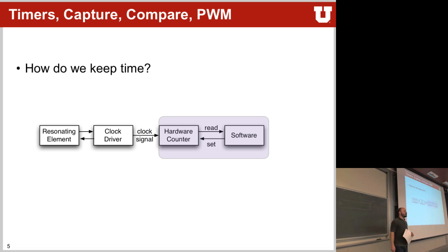What's the most important thing about your counter, though? It usually has a certain number of bits, right? N bits. For example, in your SmartFusion, you have a 32-bit counter that you can link up with a second one to make a 64-bit counter if you want to. So how does that work? How can you take two counters that are 32-bit and make them into a 64-bit counter?